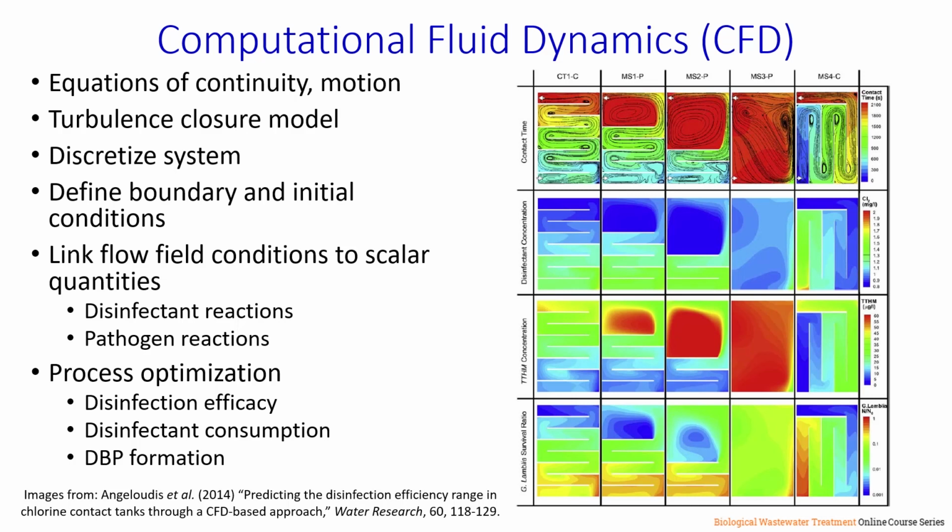If you follow these various reactor configurations, starting from the left with a highly baffled configuration, then fewer baffles moving to the right until we get all the way over to the right in this one, what we observe is that the internal baffles within these systems make a huge difference in terms of disinfection efficacy and overall process performance. And generally, the systems that are more heavily baffled provide conditions that more closely approximate plug flow behavior and that get to a much more efficient reactor design.